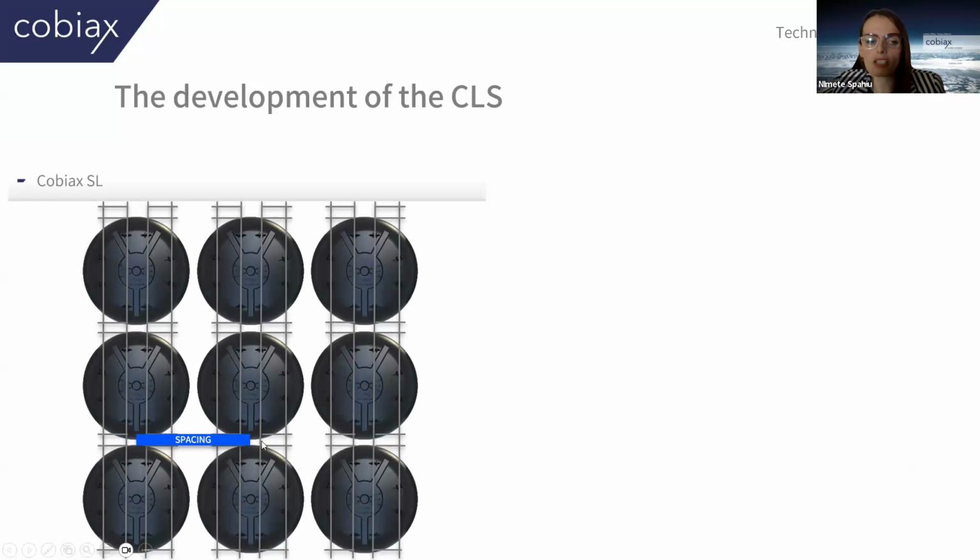And you should always save this space in here. So this space in here should be parallel to the other space in here. But this sometimes leads to many mistakes on site. It is very important to save this space and to keep the distance of 35 centimeters in all directions, because it will create this area here that is highlighted with green.